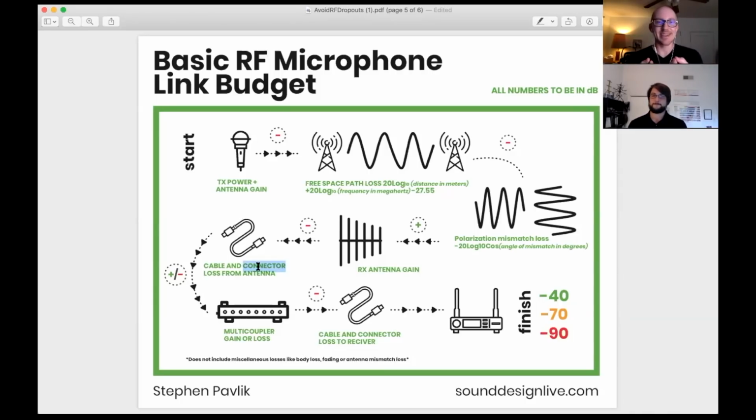How significant is that? I guess I could also look at the specification sheet for that connector? Yes, and cables and connectors do break down over time. So you can look at the specification sheet for whatever connector you have. Good connectors should be either no loss or about 0.5, which is what I've put in these. Connectors that have broken down over time can be like 1 to 1.5. Hopefully not over that. That's pretty much a broken cable or connector. But same with cables, where they get broken down over time, they exhibit more loss.